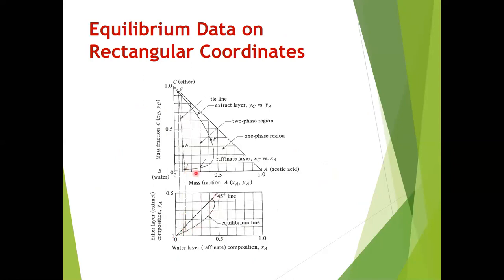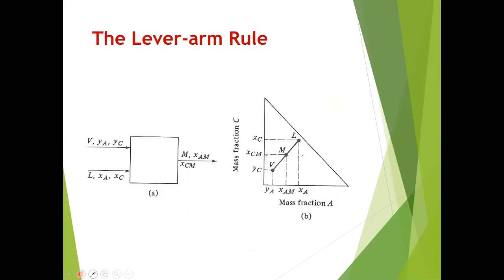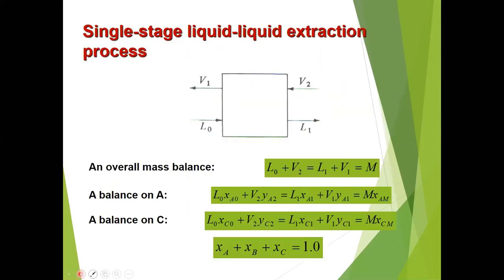That is why we say these two are equilibrated. Then you turn left to the 45-degree line and you go up and rest on the upper part of the phase envelope. If you connect this point G, representing the extract, to the point I, representing the raffinate, you have what we call the equilibrium tie line, representing that the two phases after extraction has already proceeded are equilibrated.